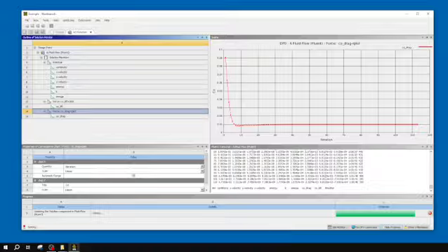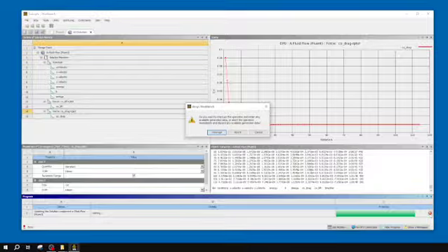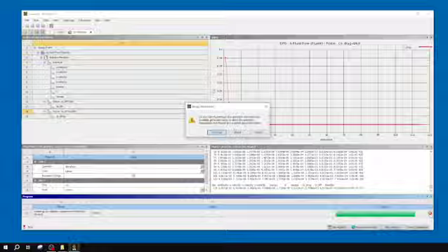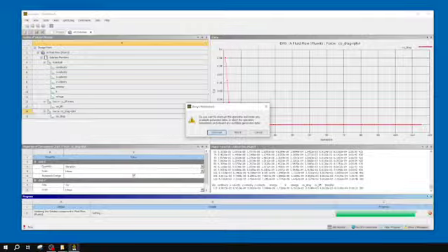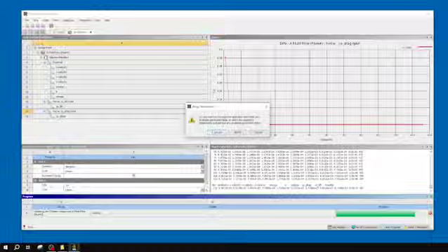Depending on your precision, you might want to let it go farther. You might cut it off early. I'm going to cut it off early for this example, though. To do so, you're going to want to hit this little X, which is a stop, and it'll give you an option to either interrupt or abort. You're almost always going to want to interrupt it. If I abort it, not only does it hard cancel the solution,